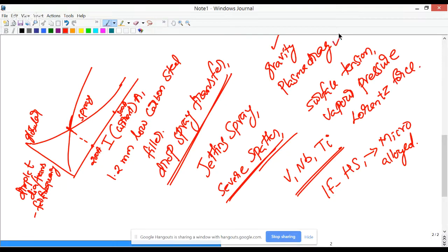Gravity and plasma drag are all process specific. Suppose you fix the process: you choose a shielding gas, a given filler diameter, the velocity of shielding gas, and the mode of welding, whether downhand welding or up-hand welding. Once you choose the welding process, these forces are more or less fixed, right? If the material composition is fixed, surface tension is also fixed. Whether you use a bare GMAW or flux coated wires, the surface tension is determined by the electrode composition. And the vapor pressure is created by the evaporation of the weld pool. This vapor goes up and then pulls or pushes the droplet in its position. So when you fix the material, this is also fixed.